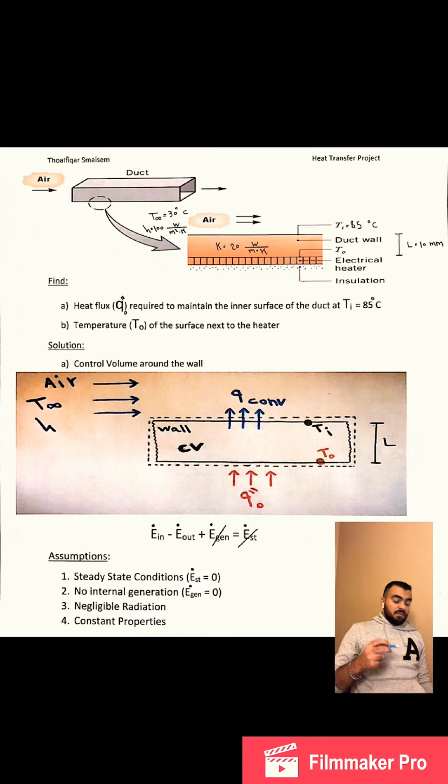So the first assumption is steady state conditions. Since there is nothing about time mentioned in the problem, we can assume it's a steady state problem. So nothing varies with time. There is no storage, so the right hand side term in the energy balance equation is going to be cancelled.